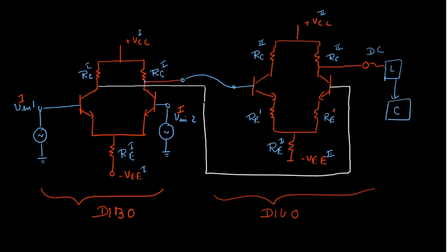So we want that the DC component here should be 0, and if there is some DC component here, we can somehow manage that. So we are more bothered about the DC component here, which we make 0, and then we further feed to the next stage, which is a class C amplifier.